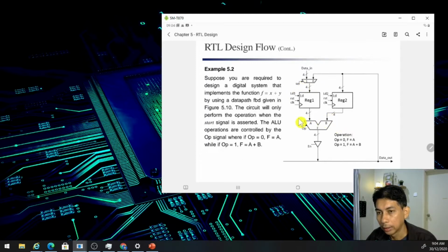So in order to write the code for Verilog or other HDL languages, for example VHDL, you need to make sure that your code will be synthesized to the correct hardware. For example, if you want to create the multiplexer, you need to know exactly that the code you write will be synthesized to a multiplexer.